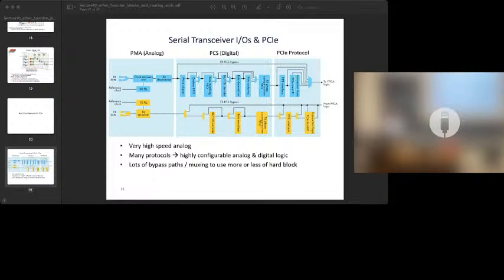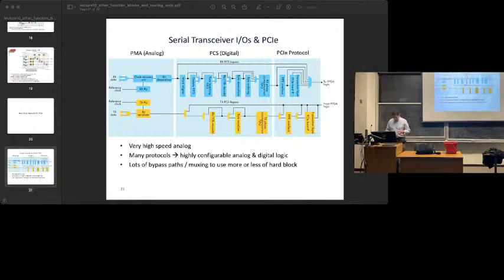The way that PCI Express Gen 2 made sure that they got a certain number of transitions is they took every 8 bits and recoded them as 10. They forbade all combinations of bits that wouldn't have enough transitions. So this has to undo that. It takes 10 bits of data and turns it back into the 8 bits they really represent.